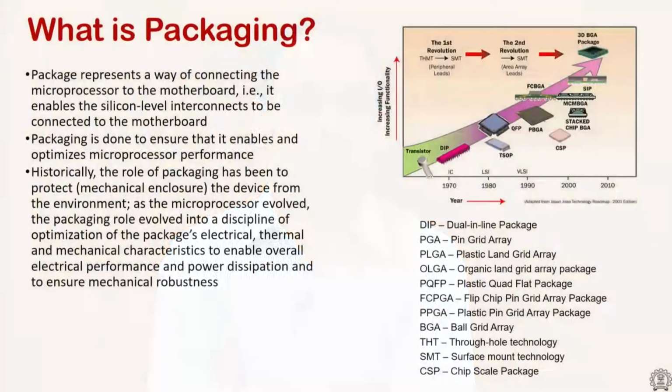and this is what a typical package means. Package represents a way of connecting the microprocessors to the motherboard, that is, to enable the silicon level interconnects to be connected to the motherboard. And often packages are done to ensure it enables or improves or optimizes the microprocessor performance. The initial role of a package was to provide a mechanical enclosure to protect from the external environment, but the role of packaging has improved so much that nowadays packaging is the critical element in the whole system. So that is what the packaging goal is.